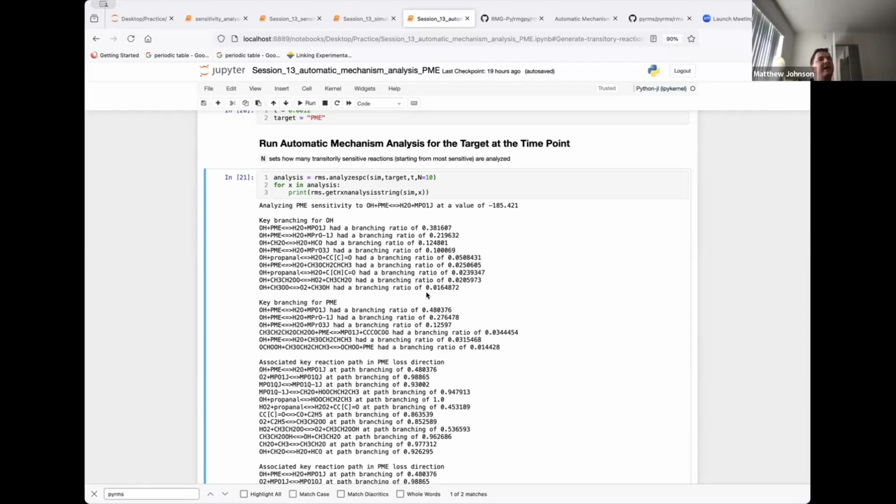For the PFR, the PFR is equivalent. The catalytic one is a little bit not equivalent, but you can devise a reactor that is equivalent in time. So essentially you can swap distance for time.